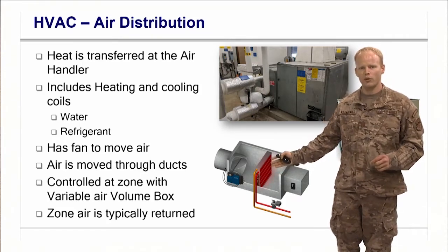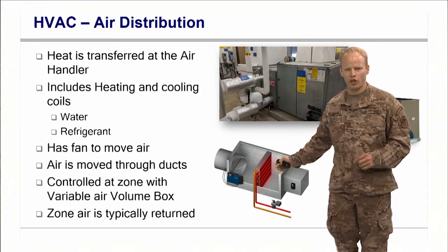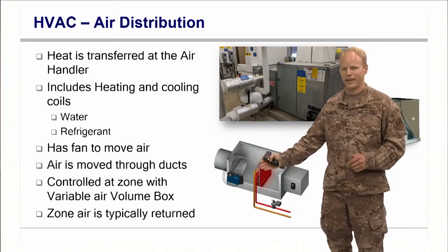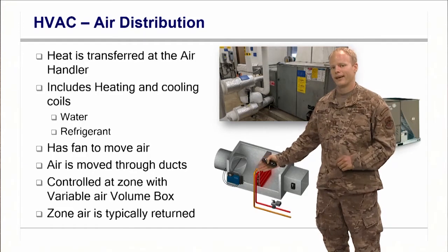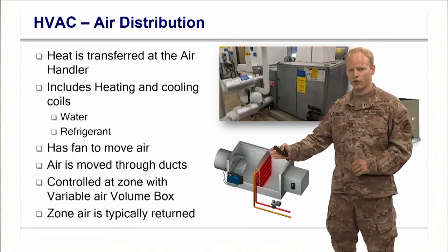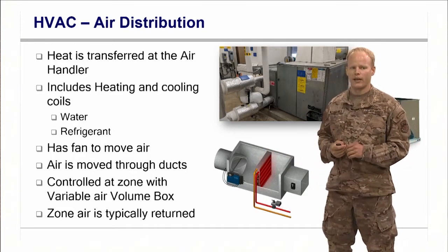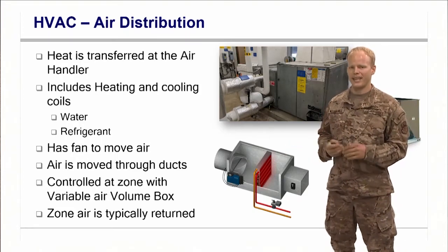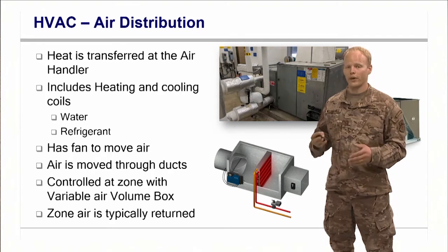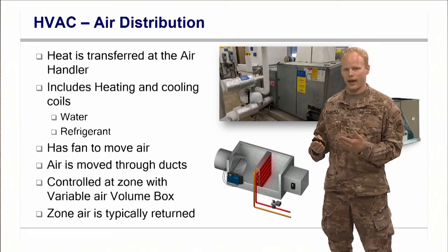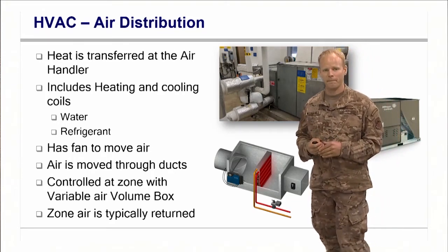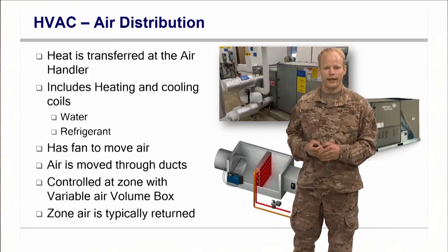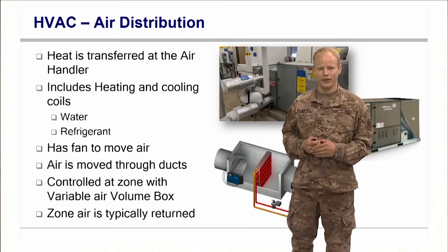And you can see we take air and we push it across this cooling coil, or this heating coil, as shown here, being red. We move air across it. We transfer heat from the water to the air, and that's how we heat up the air at this coil. We don't want the two fluids mixing, so that's why we have a heat exchanger there. This is what your coil will look like, bigger inside your air handler.